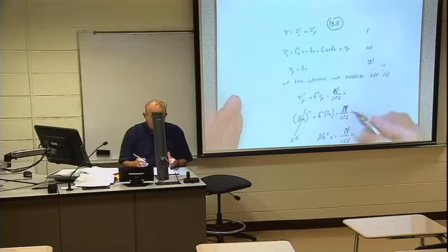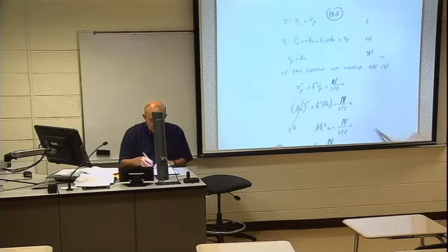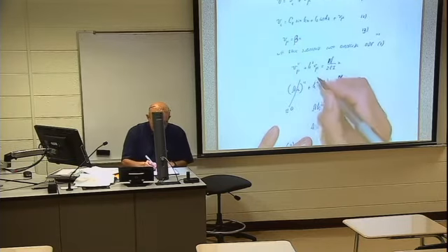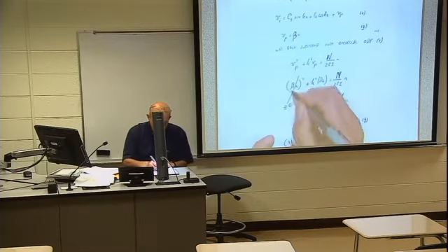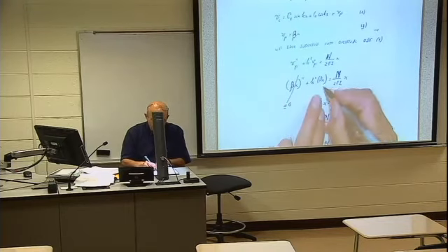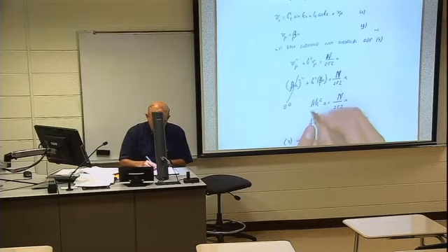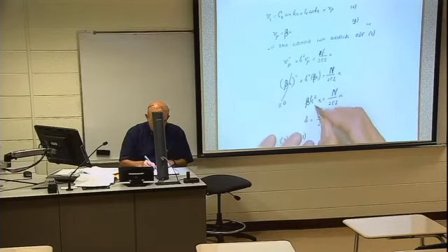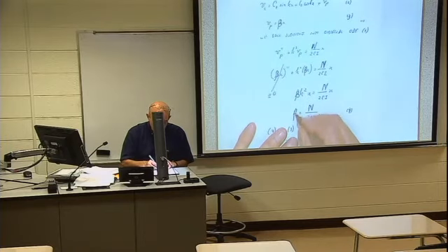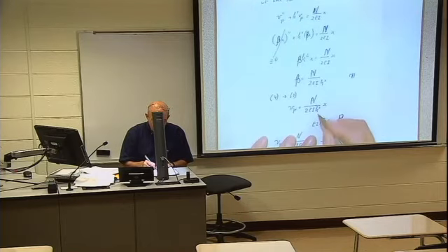Previously I denoted it as beta x. If you want, I can denote it also beta x. So I substitute, then beta x double prime is 0. This is beta k squared x, that equals n over 2EIx. So from here I get beta k squared x equals n over 2EIx, so beta equals this. So the particular solution is n over 2EI k squared x.